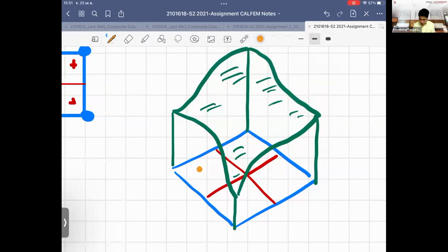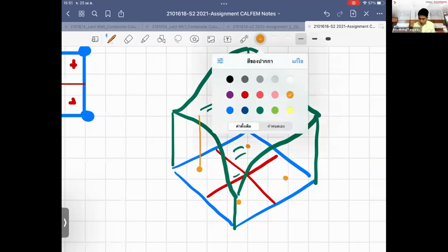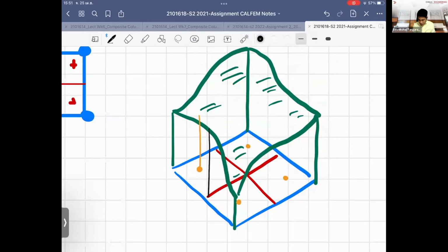This is my Gauss point here. What happens is we project the stress up to the line of the surface, and then the whole block of the quarter area that we are looking at takes the value of the average stress in this area. The stress value that they take is coming from the Gauss point. So you approximate the stress, not over the whole surface, but you discretize the whole surface by using the fixed stress at the Gauss point.